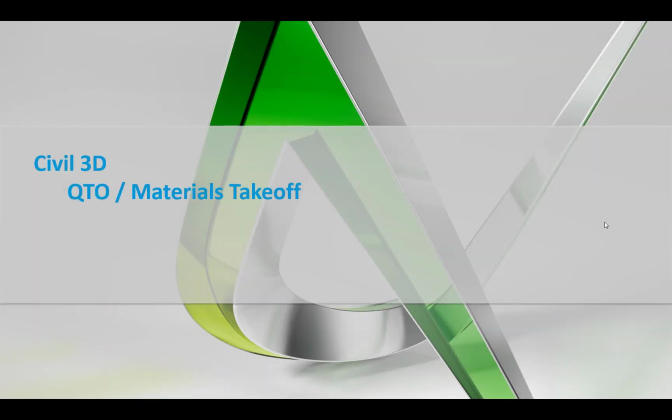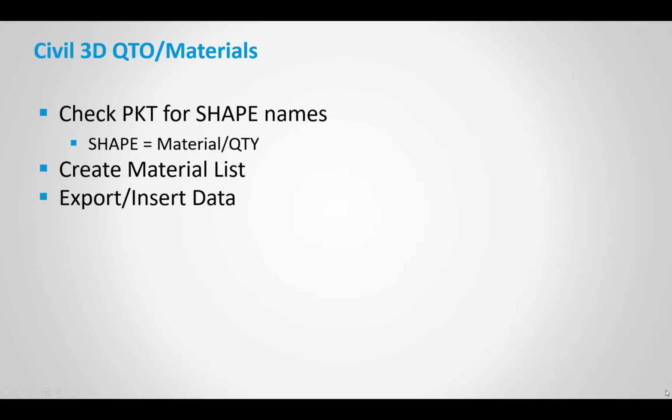Hello, in this session we're going to look at QTO, quantity takeoff, and some material takeoff. So as you go through and bring this into Civil 3D, some of the things to look at first would be to check that PKT for your shape names. In Civil 3D, as you're aware, the shapes equal a material or equal a quantity. So if we have not created a shape within our subassembly composer file, it will not do the quantities.